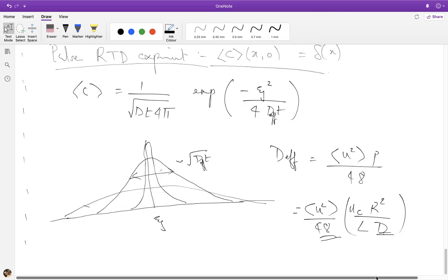The utility of the method that we have used today, to do the same theory and arrive at the same theoretical result, is that it can also be applied if we include a nonlinear reaction in the process to model an actual tubular reactor. This is something that we will take up in a subsequent lecture. And so the utility of this method is much broader than either Taylor's simplified argument or Aris's method of moments, although the method of moments also has had quite wide utility in several problems.